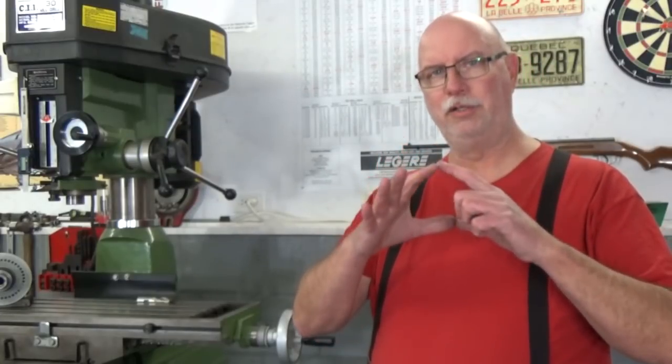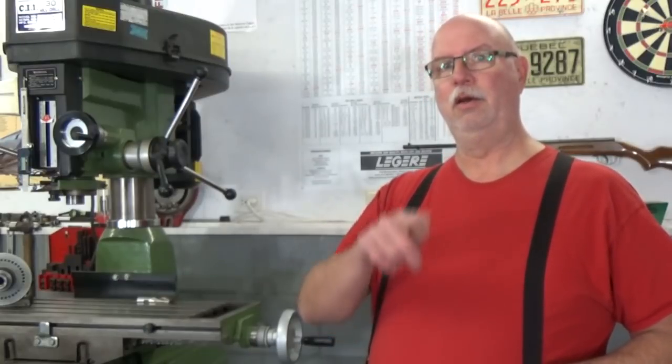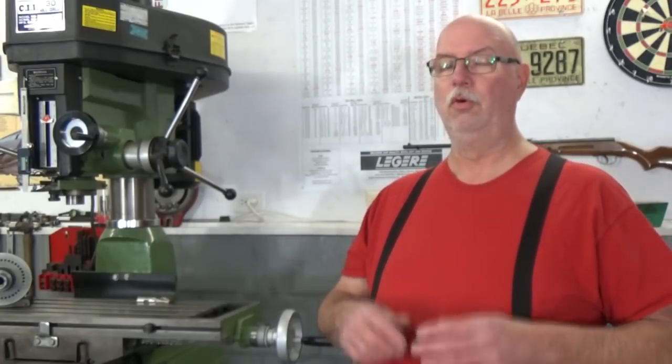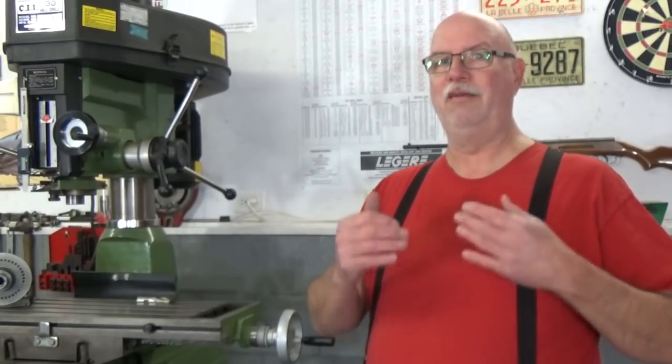If I say that I have a screw that is 1/4 20, so it's an imperial screw, and it has a 1/4 inch major diameter, and it has 20 threads per inch, the pitch of that thread is not 20. The pitch is how far a thread advances axially in one turn. So if I turn a 1/4 20 screw one full turn, it will not advance 20. 20 isn't a dimension, it's a number. What it is actually is the number of threads in 1 inch.